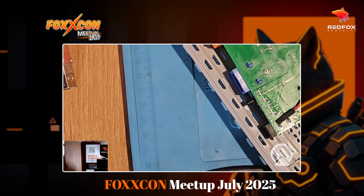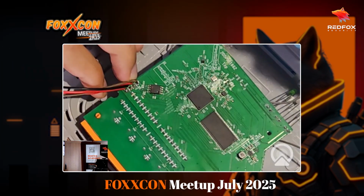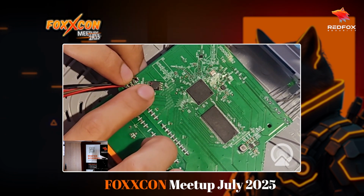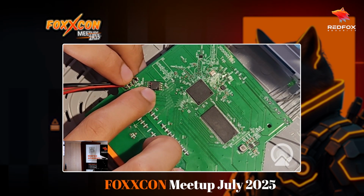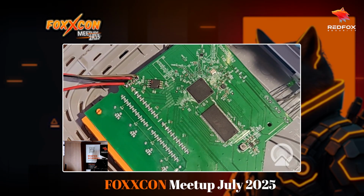For that, instead of a solder, we'll be needing a heat gun, because the chip that we'll be removing right now, as I said, this is your MediaTek processor, this is your Wi-Fi chip right here, and this is your NAND flash. This is where the data is stored. This is what we want. Okay, so we'll be taking out this chip today, and for that we'll be using a heat gun. I'll just do that.